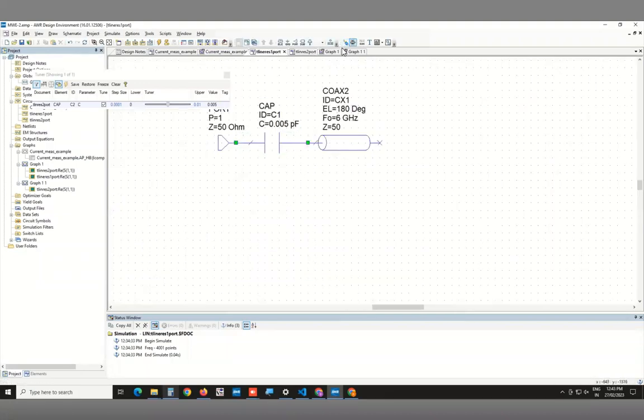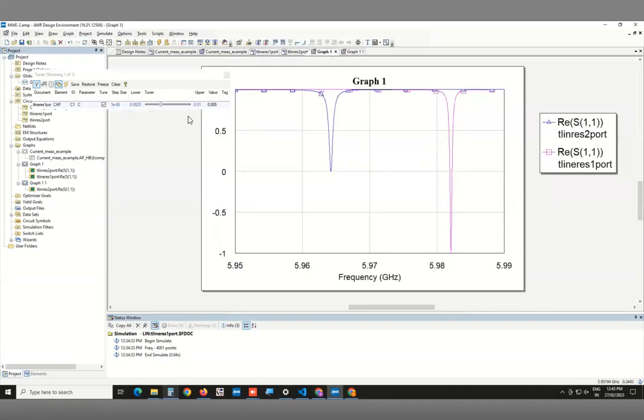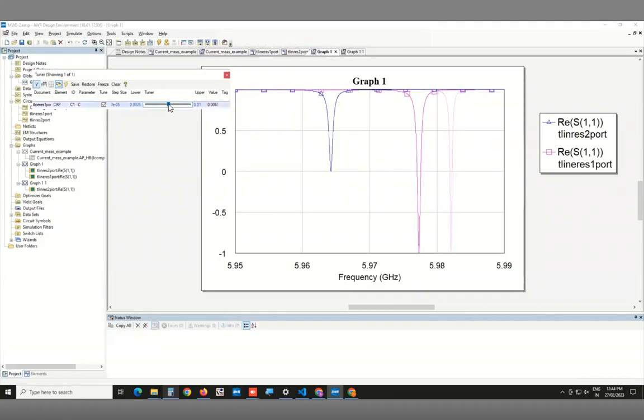Right. So I'm going to put a tuner here, and let me get rid of this guy to prevent confusion. I go back here and I start to increase, because I need to bring this lower, I have to increase this frequency. But remember, this is still going to remain from +1 to -1 because it still is a one-port circuit.